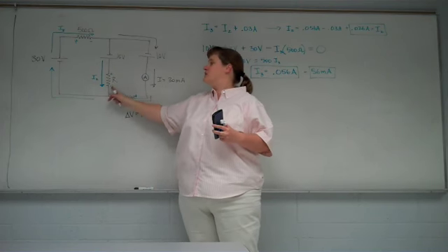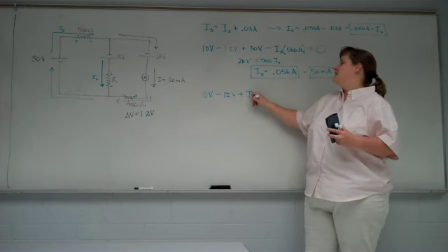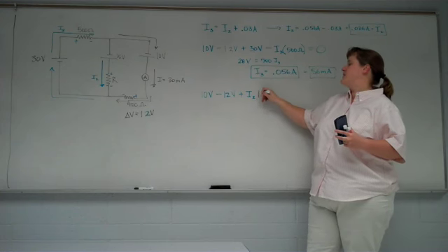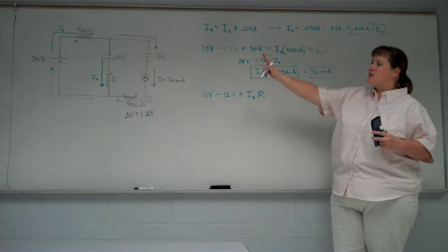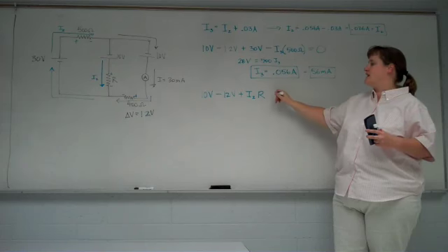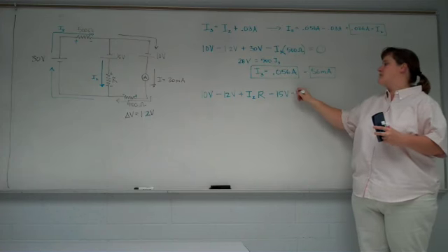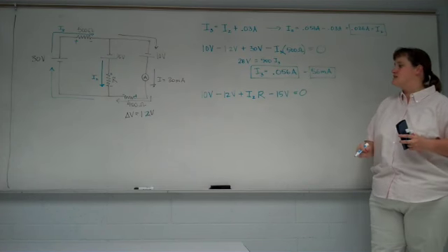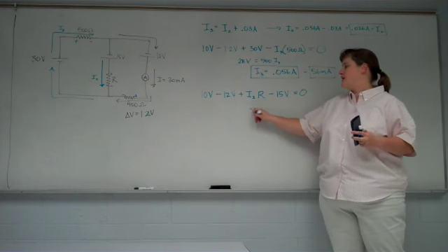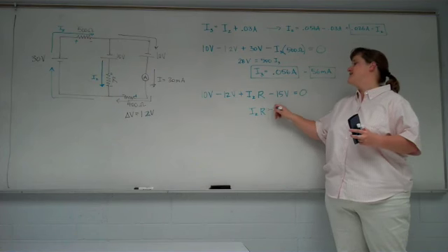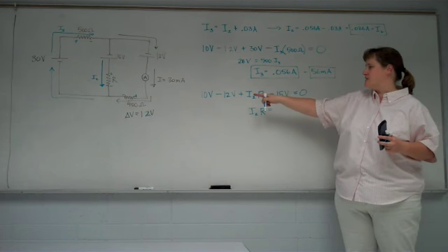Going up through the middle, we're going negative to positive, so we're going to see a gain. Its voltage depends upon I2 and its resistance R. Keep going up, we're going through the battery, we're going positive to negative, so we're going to see a drop of 15 volts. That gets us back to where we started, so that all has to equal 0. So I2R has to equal, bringing all this to the other side, negative 5, negative 17.